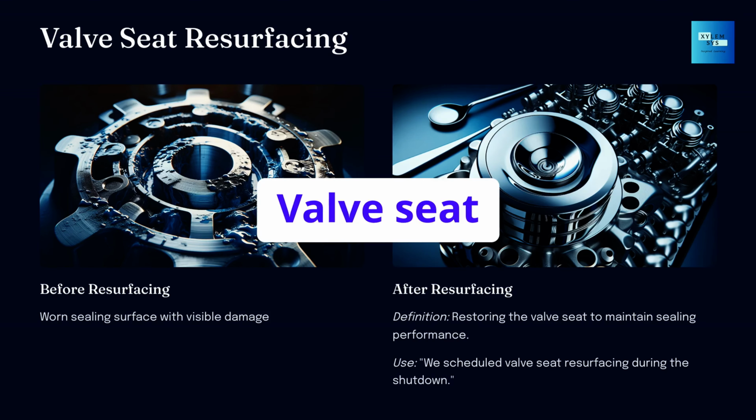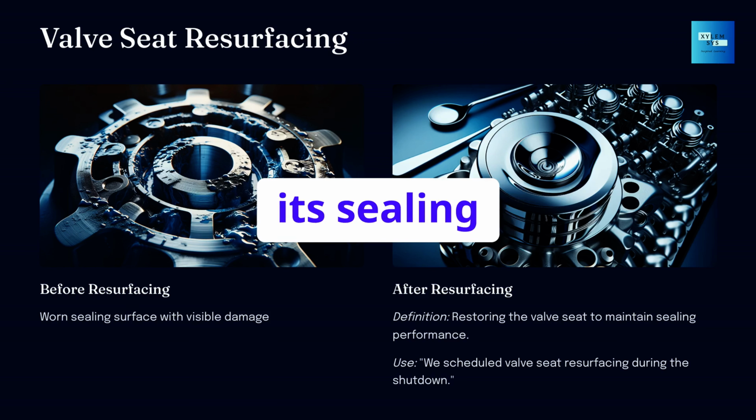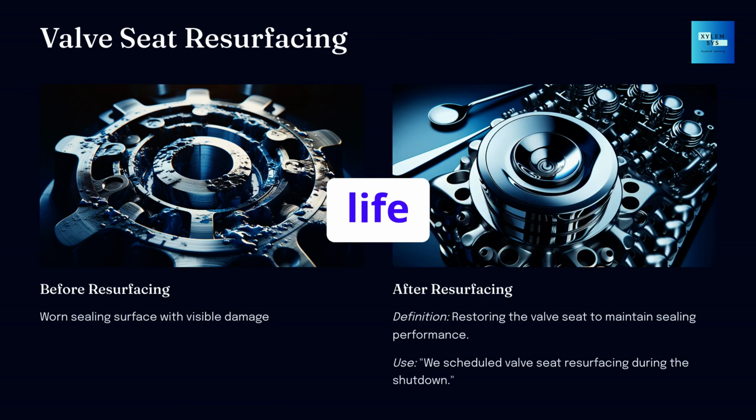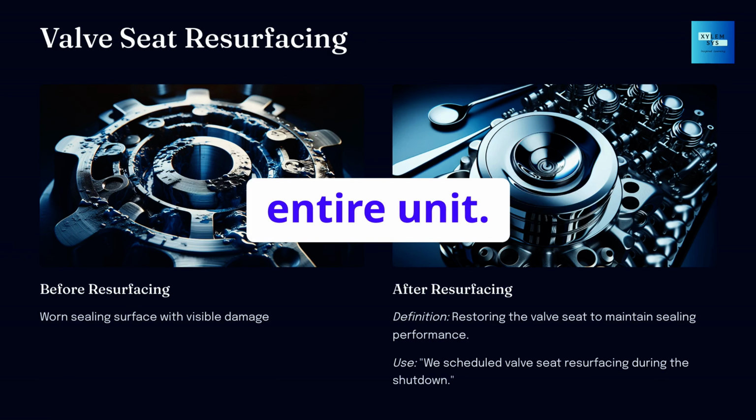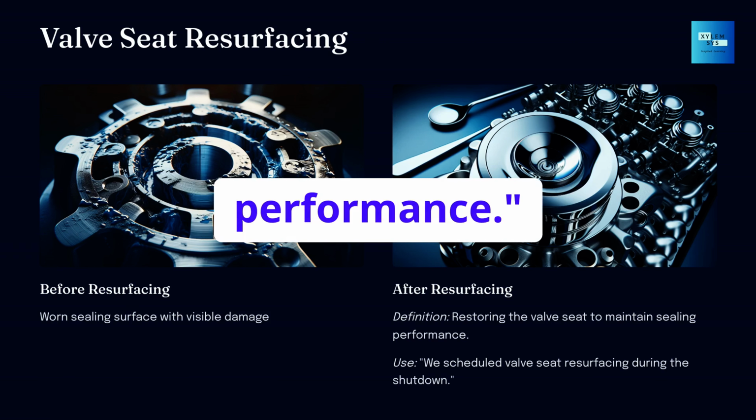18. Valve seat resurfacing. Resurfacing the valve seat restores its sealing surface, extending the valve's life without replacing the entire unit. We scheduled valve seat resurfacing during the shutdown to improve shutoff performance.